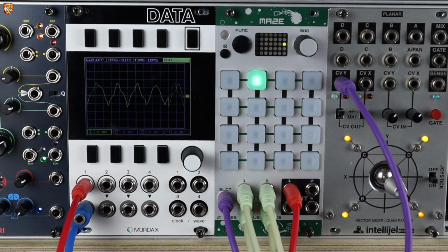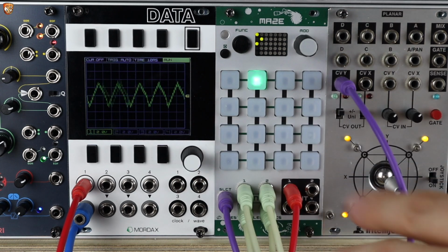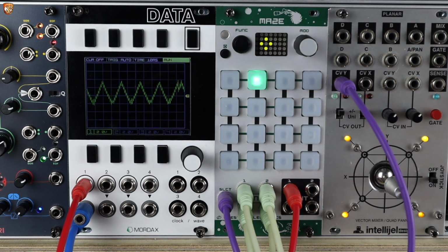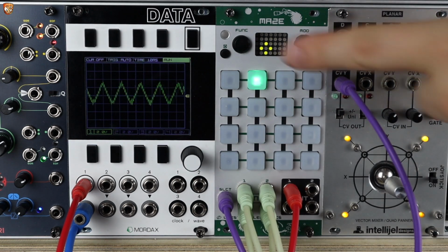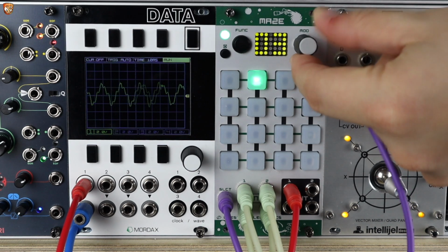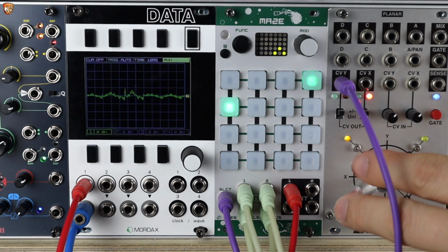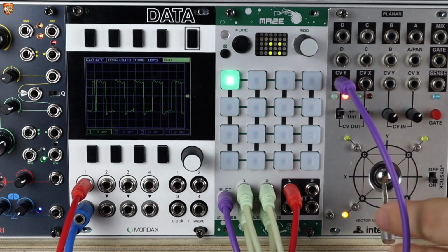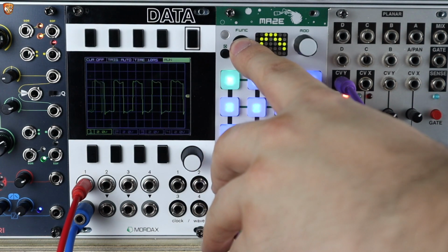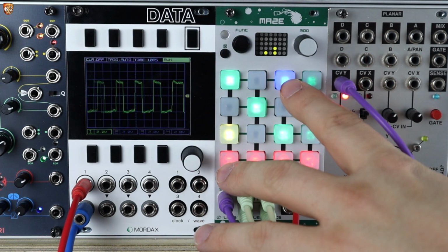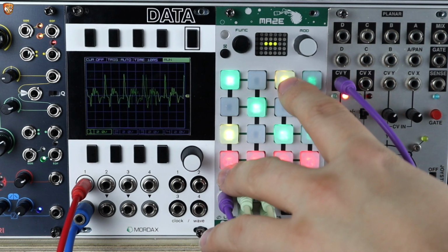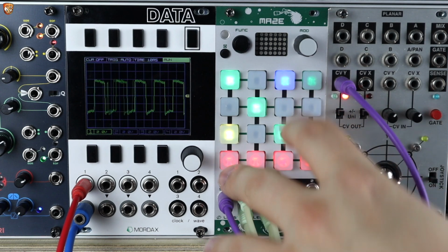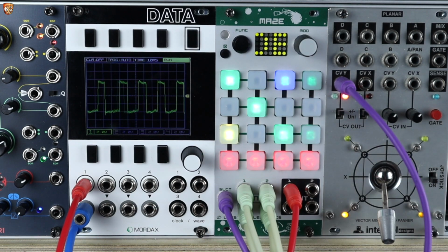And this is just a really simple patch to demonstrate the fading. As I said, you could have complex 16 parts saved. The fading, like the other select driven functions, is controlled by the encoder, which lets us set the range of that select input. And holding the button to get into settings, we can see when this is blue, we're in fade mode.